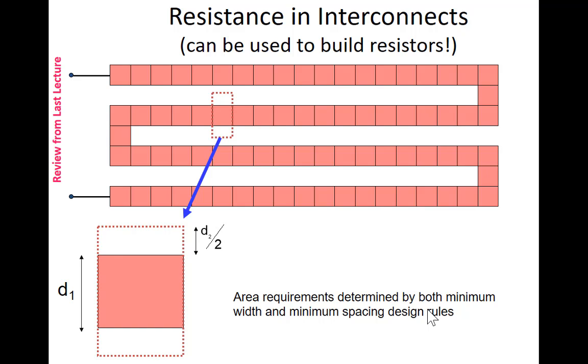That's a good question. And I didn't analytically show it, I just stated it. But if you have a conductor or a resistor that turns a corner, and you look at where the current's going to flow, it's going to flow pretty much uniformly out here throughout the whole region. And down here it's going to go pretty much uniformly, but it's going to crowd around the corner.